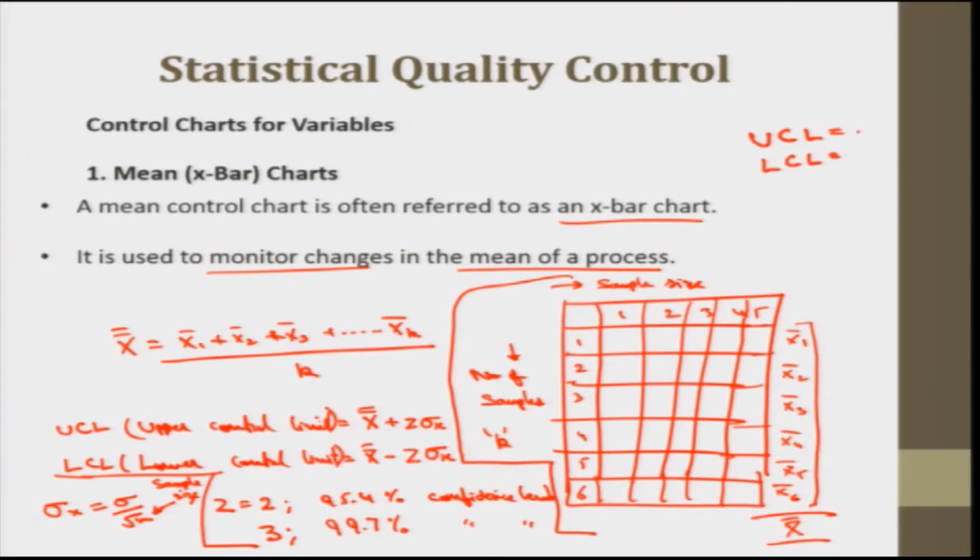So, the upper control limit here can be given as x double bar plus A2 into R bar. Because I need to plot both the charts, I will calculate the R value and then calculate this value. So, the lower control limit is x double bar minus A2 into R bar. So, these constants are connecting the x bar chart to the R chart.